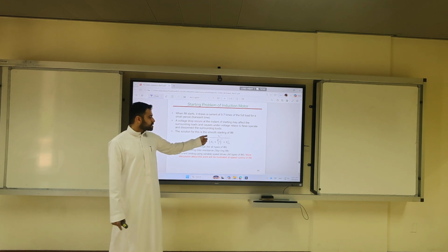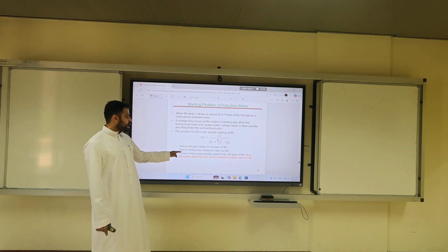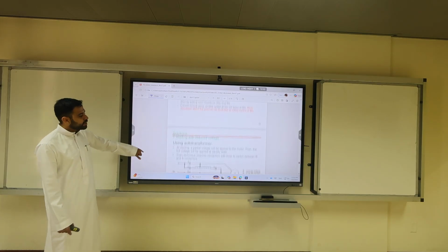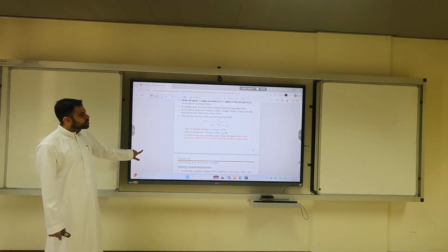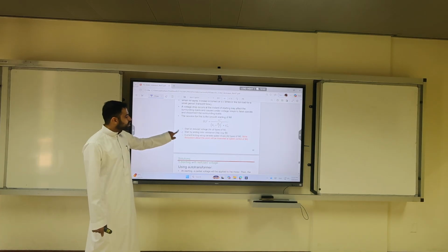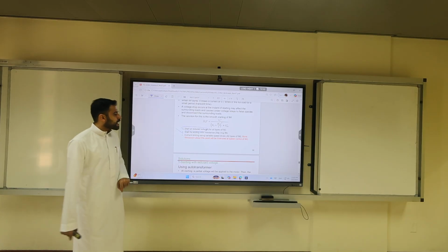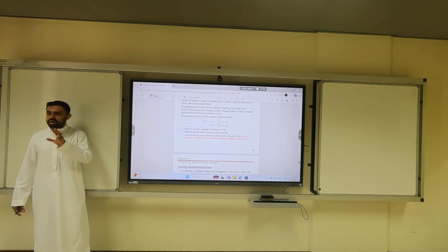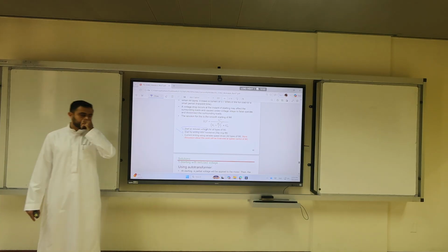The solution for this is to smooth start the machine: reduced voltage, adding resistors, current limiting. This is the same slide, but written in a different way. Now, one of the solutions is adding resistors, but one of the other solutions is reduced voltage. How can I reduce the voltage? So let's learn a few tricks on how to reduce the voltage for starting of the machine.